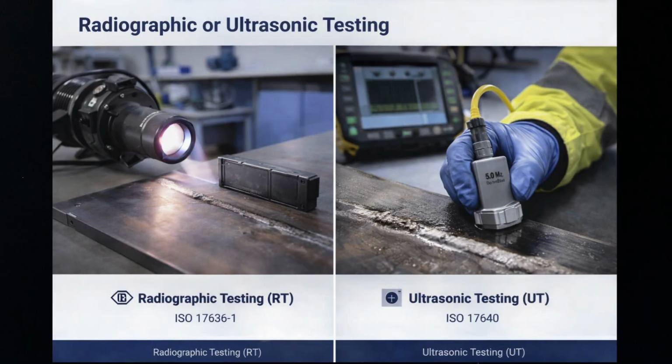Radiographic or ultrasonic testing. 100% of the weld must be subjected to either radiographic testing, RT, or ultrasonic testing, UT. RT is governed by ISO 17636-1, film-based, or ISO 17636-2, digital detectors. UT is governed by ISO 17640.